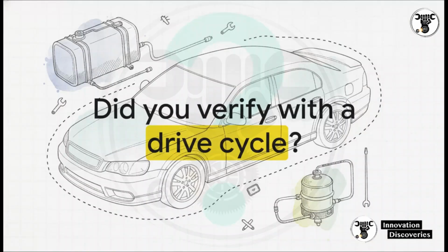And finally, our last question. I really want you to think about this one as you head back to the bay. After you install the new part, are you just erasing the trouble codes, handing the keys to the customer, and hoping the EVAP monitor's set? Or are you actually verifying the repair by taking the car through a complete, specific EVAP drive cycle? Remember, just erasing codes doesn't fix the car, and an incomplete readiness monitor is still an automatic emissions failure.